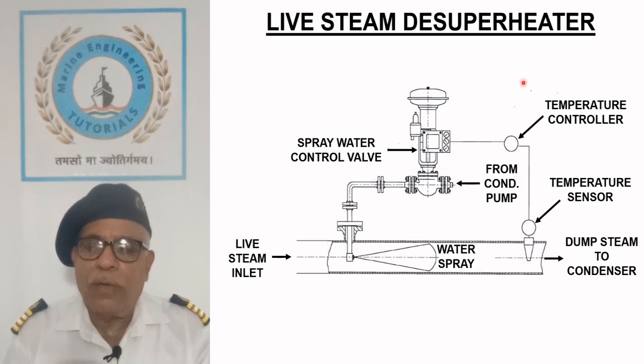Temperature controller senses the steam temperature before condenser and regulates the flow of spray water through control valve to maintain desired temperature.